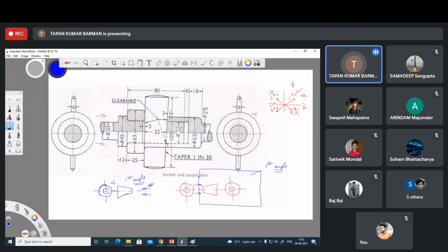See, in different directions, different ways we can take the projection, but it should be clear to you. Yes, sir. From any direction, if I take it, what should be the angle? First angle or third angle? Here, for this case, I have taken the projection from this direction. If I place the projection here, at this position, then that should be your third angle, because I have placed that side view towards the viewer.